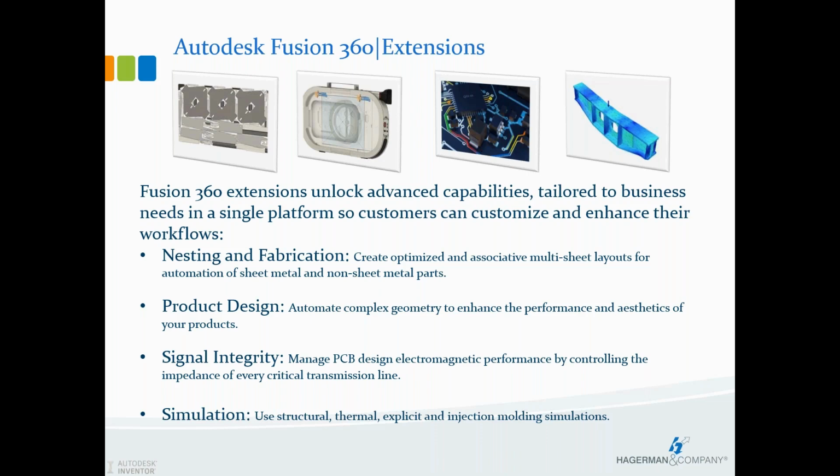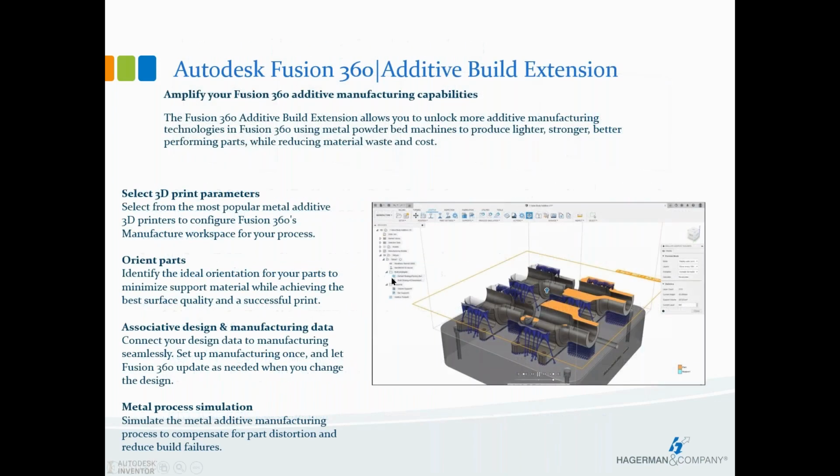Signal integrity extension, managing our PCB designs, managing the electromagnetic performance by controlling the impedance at every critical transmission line. And finally, the simulation extension gives us additional tools for structural analysis, thermal, explicit, and injection molding simulations. So I'm going to dig deeper into each one of these.